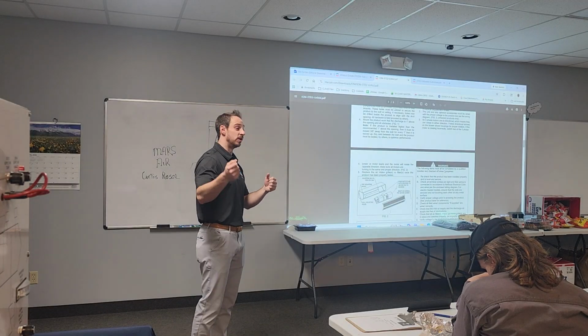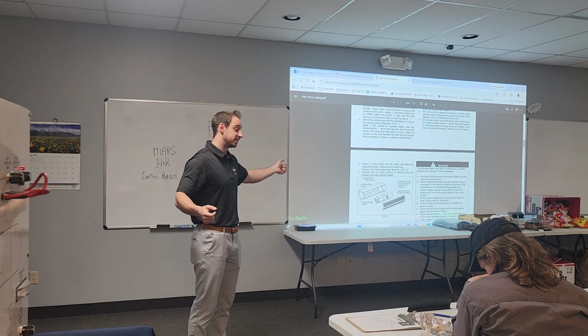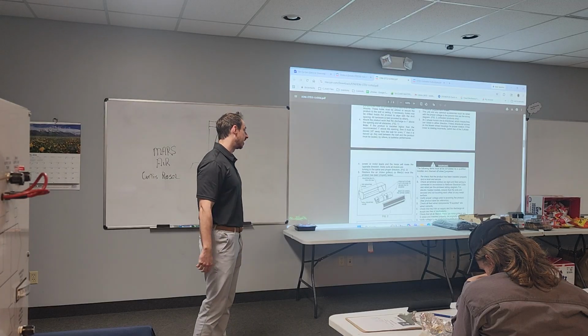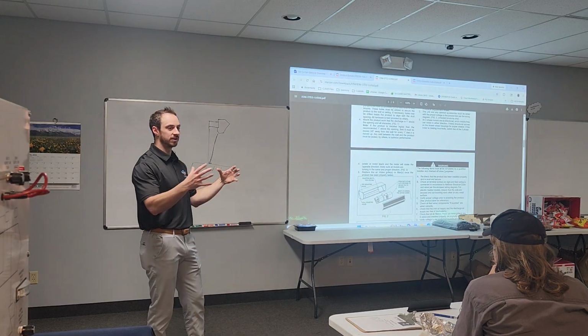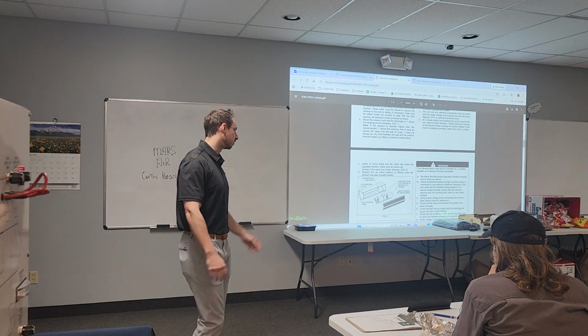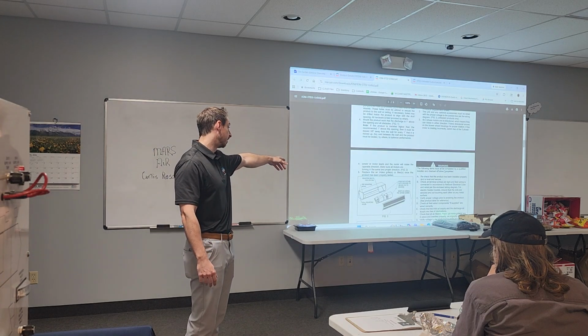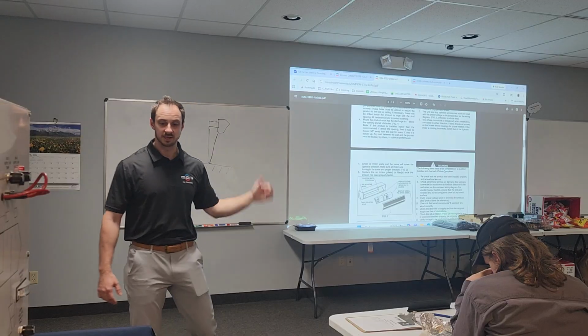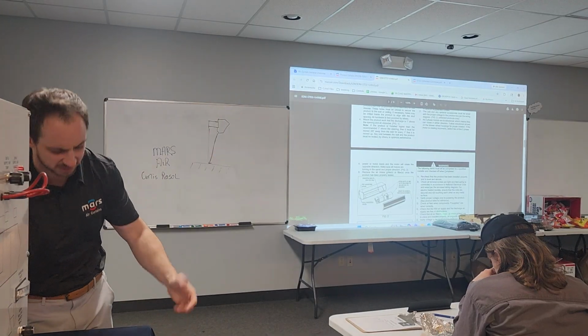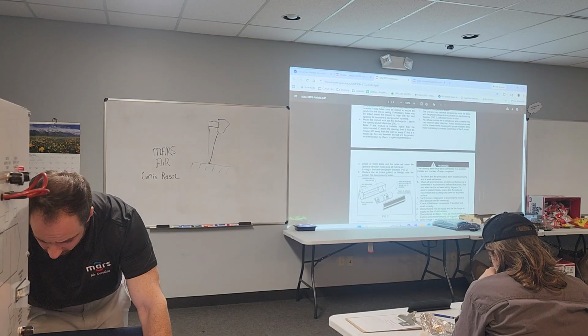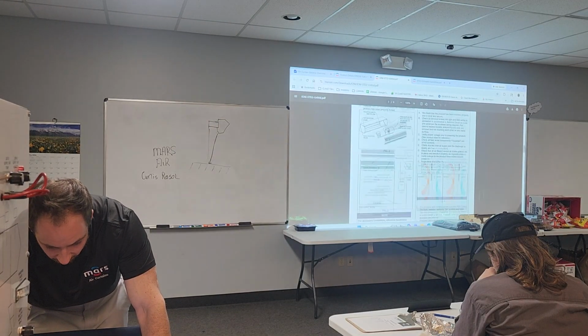If you got a 12-foot unit with the motor fan assemblies in it, you're going to need at least two guys putting that up. This way, they're lighter individual pieces, and you basically screw the motor fan assembly into the housing. So they can mount the housing and then put the motor fan in. It's a little safer that way too, and you usually can do it with less manpower.